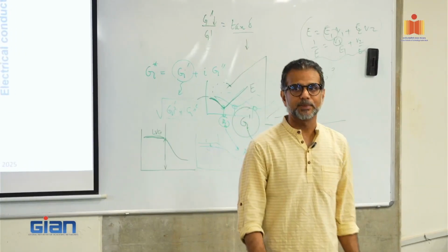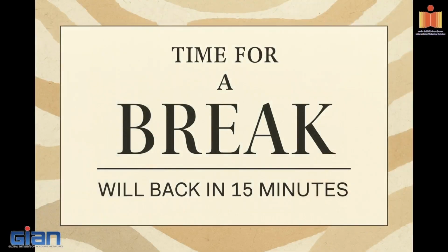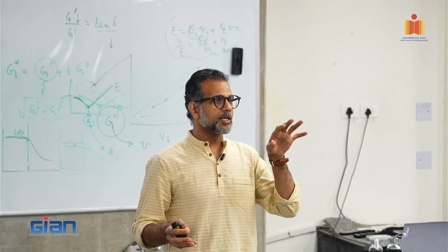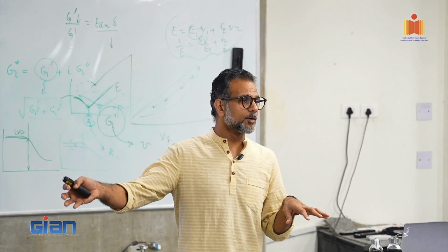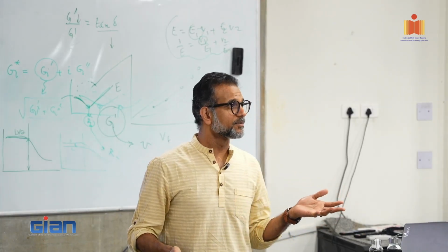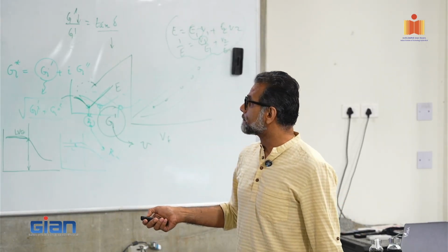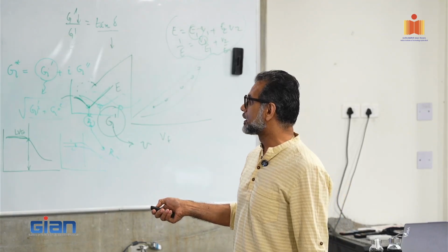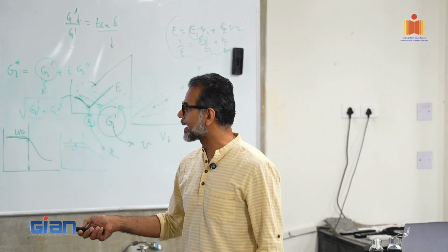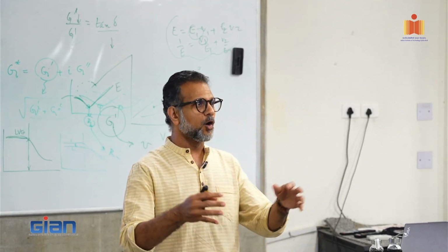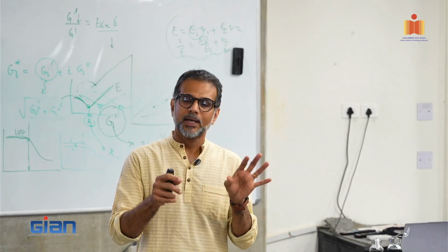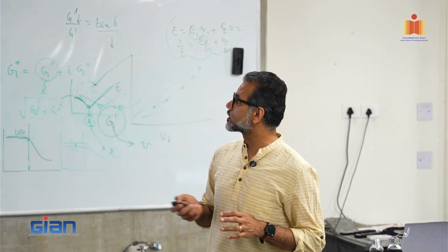It's difficult to measure. Test procedure and protocol are very important. You can't do shear rate control today, stress control tomorrow, something else the day after, and say I'm getting three different values. You will get three different values. Interpreting material behavior across multiple tests can sometimes yield conflicting conclusions, further complicating decision making. This happens all the time. When we have all the toys, you don't know which toy to use, right? And then you get confused. So it's important to stick to a certain way.